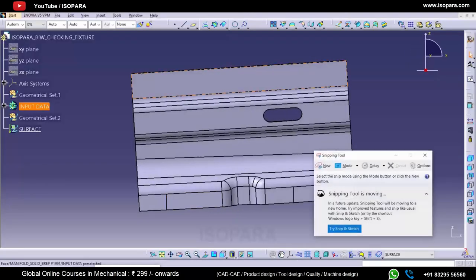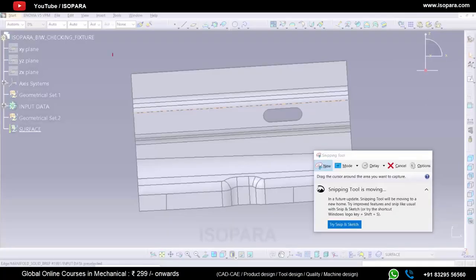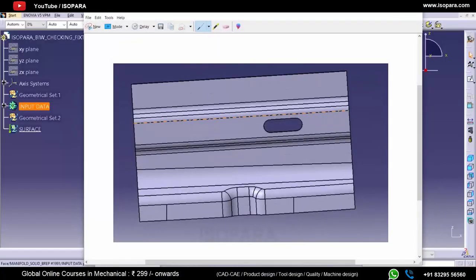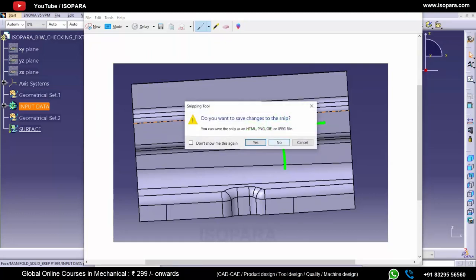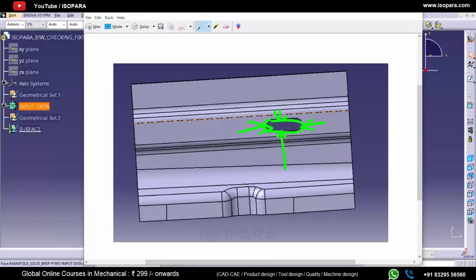the locking. I will show you the pin locking. So this is the elongated pin. So this is the pin. So this direction is locked and this direction is locked, and it will not rotate also, because if the pin was round, then there could have been a rotary motion, but we are using an elongated pin, so there will be no rotary motion.